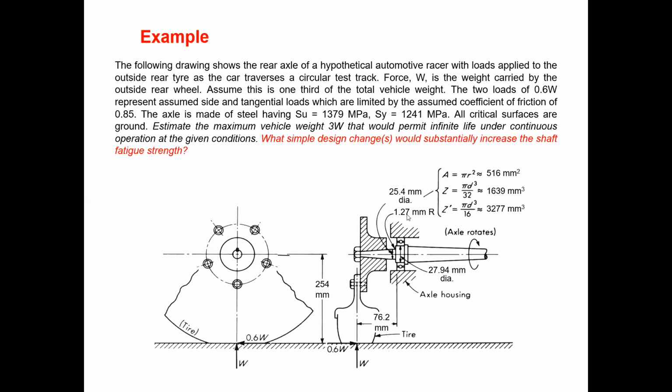And the last one, Akhil, as you told, your answer is a little bit closer, so you can improve the strength using some kind of technique. Yeah, we can use that part also. But it is not good to put holes inside the shaft sometimes. You can use another technique to improve the stress distribution. So normally what we are going to do is change the stress profile and put the fillets. So what I meant was, you know how in those pieces the diameter changed. I think the design was a fillet, but it changed from one diameter to another. You want to tell that? Okay, I understand.